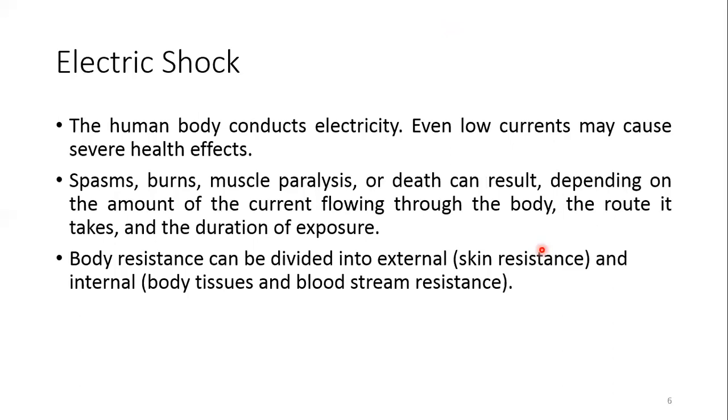The main safety should be against electric shock. Because the human body conducts electricity, even low currents can cause severe health effects like spasm, burns, muscle paralysis, or even death. This depends on the amount of current flowing through the body, the route it takes, and the duration of exposure.